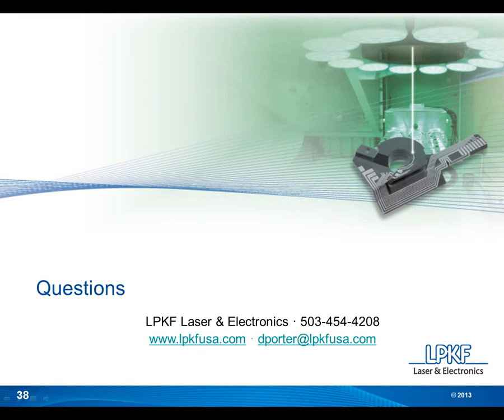Yeah, you can do that. It's very common to overmold a metal part within an MID, and then you can plate right up to that. You could also drill down to it. I'd say it's more common to have a pin that comes out of the surface, and then you would just pattern up to that pin, and the plating would continue on to the tip of the pin. But you could also drill down to it or mold a via down to it.